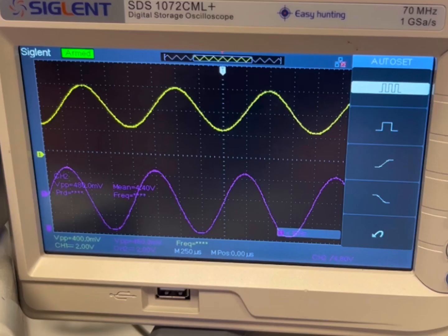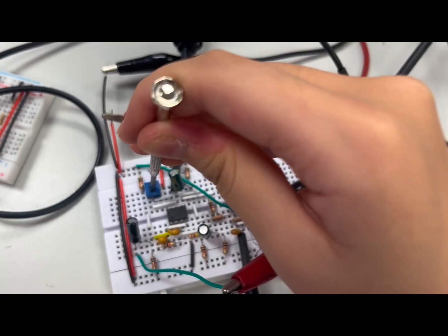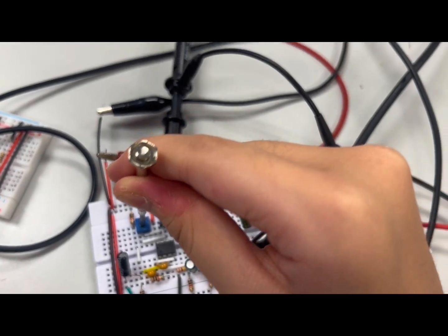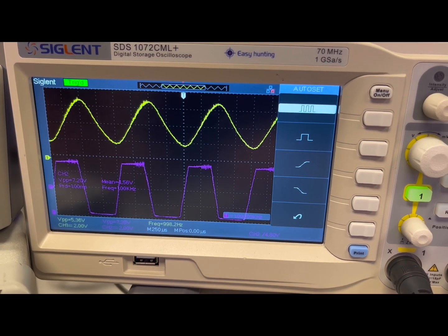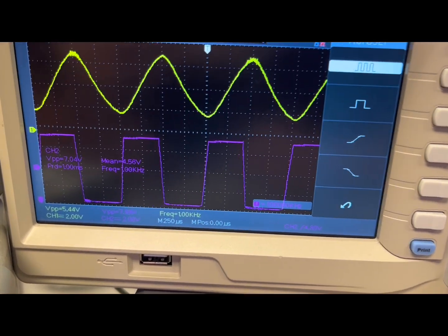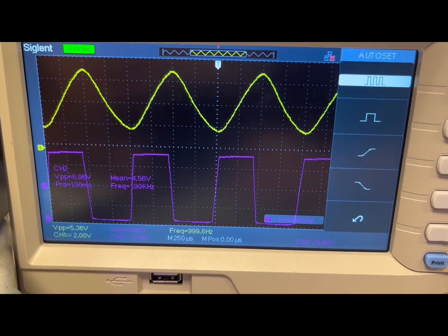To set up stage 3, we will place the oscilloscope probes in both TP3 and TP4 and leave the power supply and function generator untouched. There, we can get a filtered output voltage of 4.4 volts. The output waveform at TP4 will be determined by the output waveform at TP3. So, by turning the trimmer in stage 2, we can see how the output waveform is being affected.